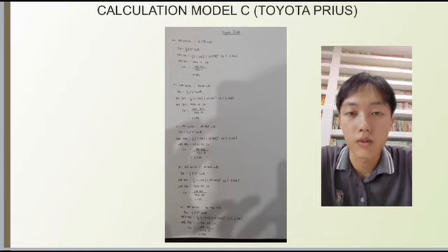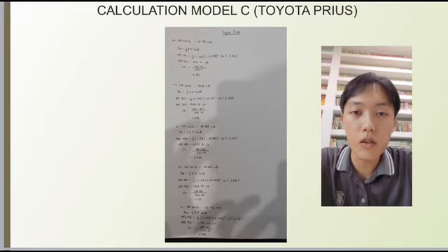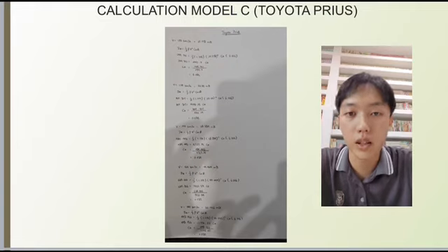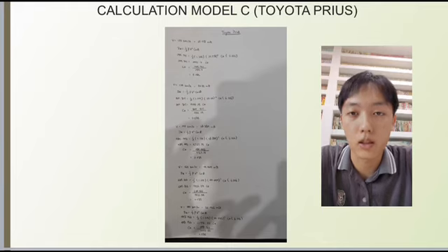Frontal area we get 6.226. So after we substitute all the numbers in it, it becomes 249.741 equal to 1/2 multiplied by 1.225 multiplied by 27.778 squared. CD we just put there since it's still unknown, and for A is 6.226. So after we calculate it, we get 2942.5 CD equal to